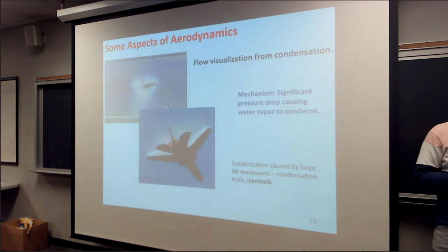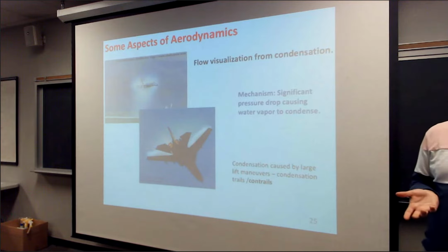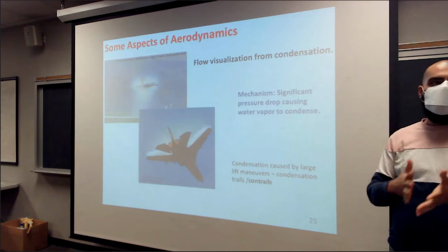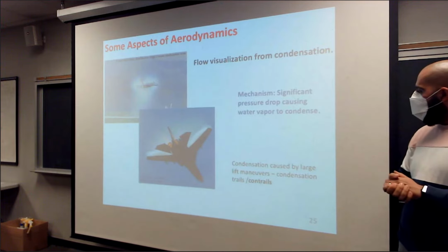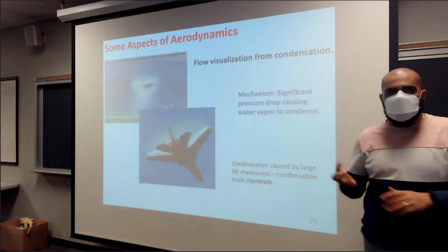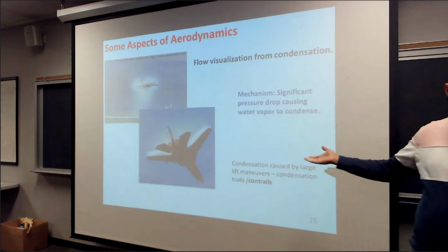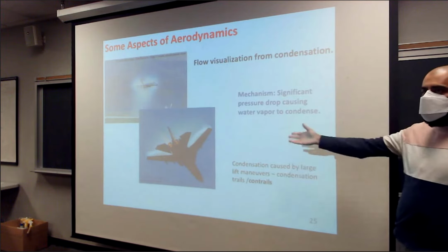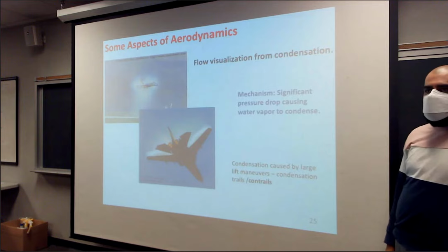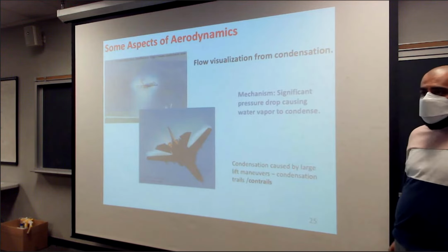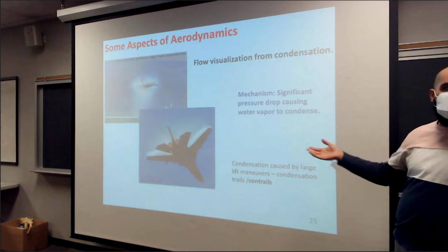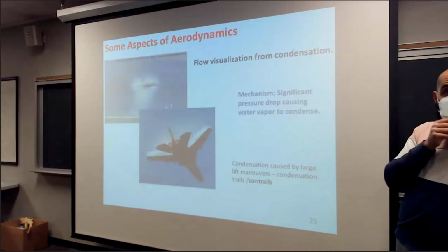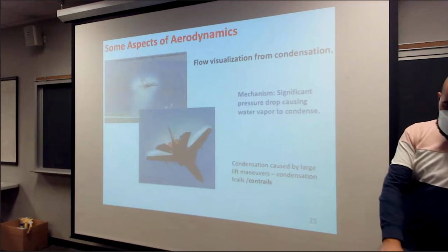Before and after a shock wave, you see a huge pressure difference, because it's a combination of a lot of pressure waves. That huge pressure drop causes condensation, which appears to our eyes like a fog. Does it make sense? In aerodynamic analysis, we're going to see why this happens, how it happens, and the mechanism behind it.